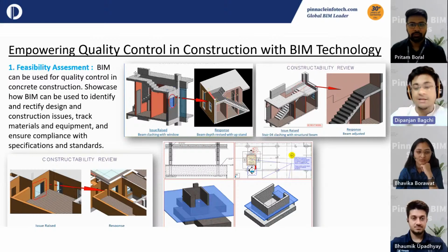So this helps in rectifying the designs and potential issues in the early stages, which they can identify through BIM. And the last one you can see is one of the running projects that we have faced. You can see at the structural section on the sump pit area, the slab is completely intersected with the core wall. That's not going to be built, guys.